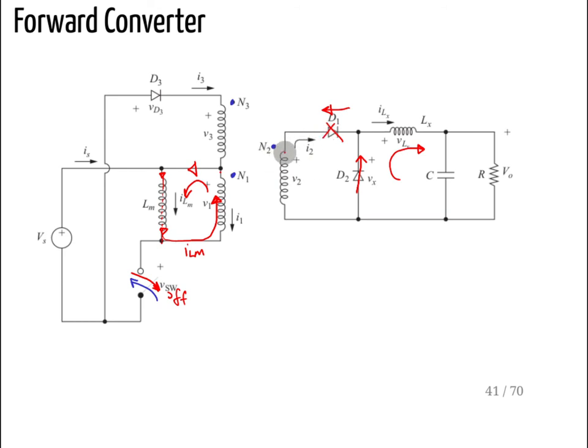In the normal case, D1 is blocked because I2 was 0, but now it is blocked because it would like to draw negative current, right? But that polarity is coming into the dot, and that will induce some current through that path, right?